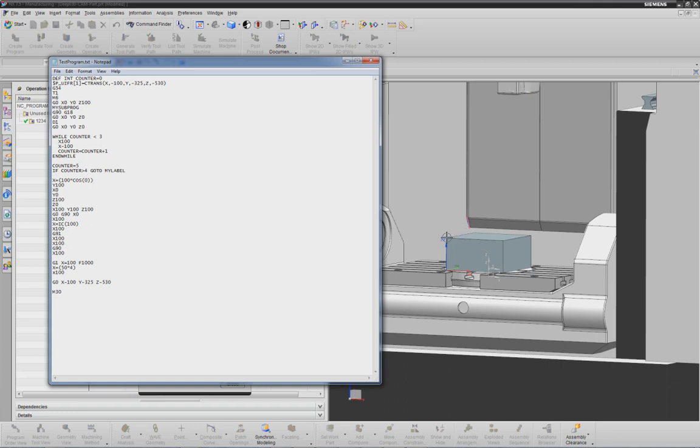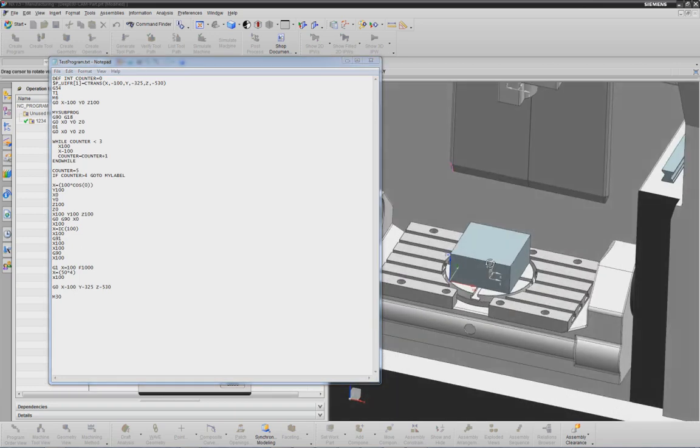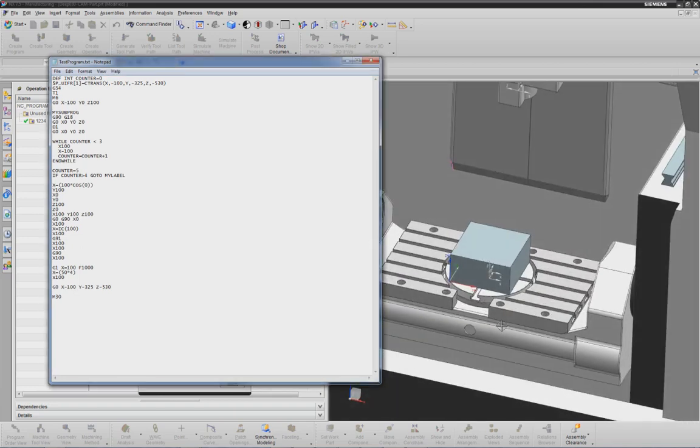This should be now exactly this position. Since I would like to activate cutter compensation, I need to go a little bit in X direction next to the part. So let's go onto the safe side, minus 100. In the end, I will use contact contour, so I will program the actual contour that I want to see.